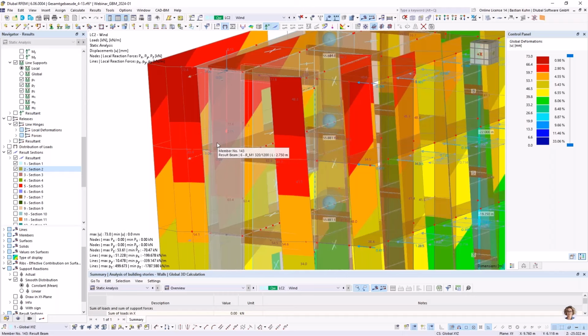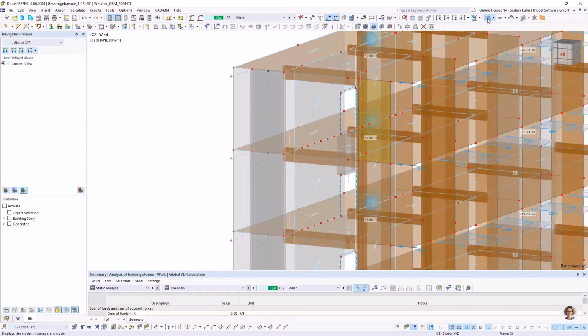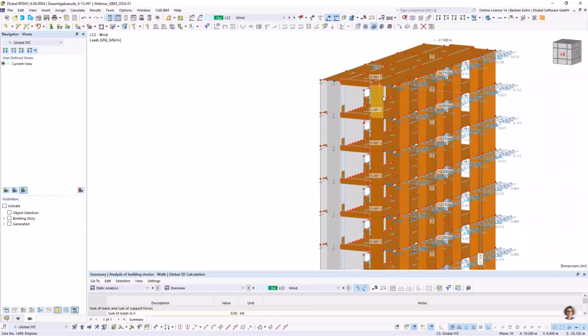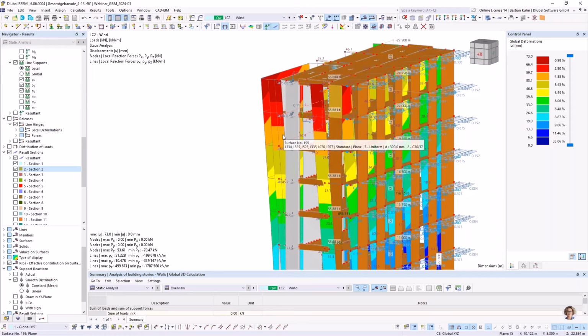And whatever you define how the shear wall looks is up to you. When I'm saying, okay, this wall in here, for example, I don't want to bear any force, you can always deactivate it by the structure modification, or you can reduce the stiffness of it. So this would all be possible, but it is in this 3D calculation, but you are looking onto it only in 2D, on slabs and walls. So this is how you would do that. Okay.